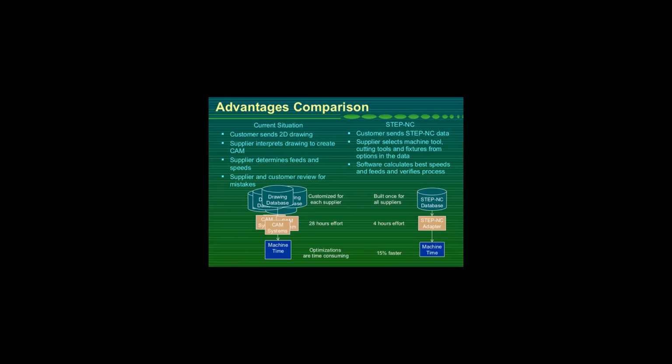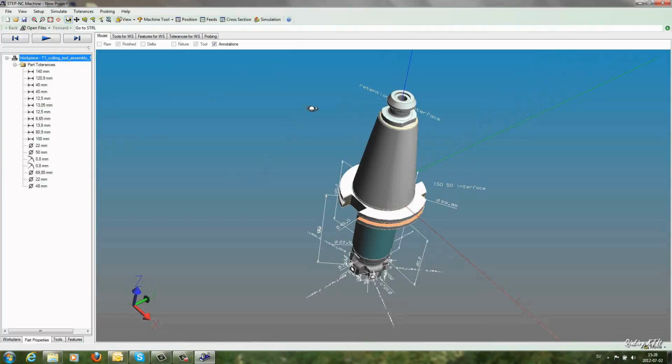In 2012, the testing focused on machine tool accuracy calculations, culminating in a demonstration in June at the KTH Production Engineering Labs in Stockholm. The test case milled a forged blank for a crown wheel gear on an older Mazak VQC20. Accuracy data from the machine was combined with tool engagement information from the STEP NC to predict the deflections, which were tested against actual machining results.